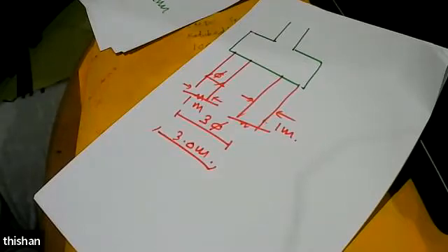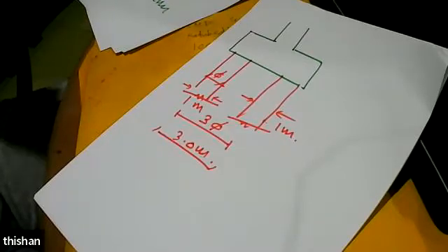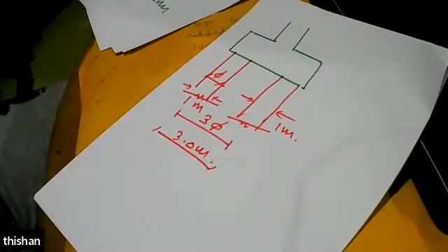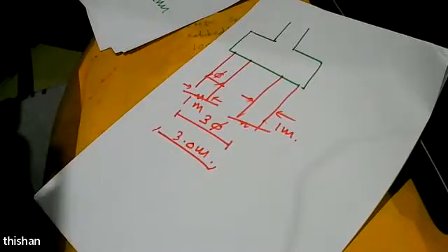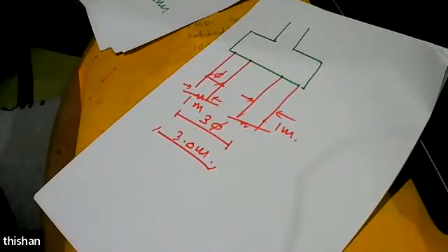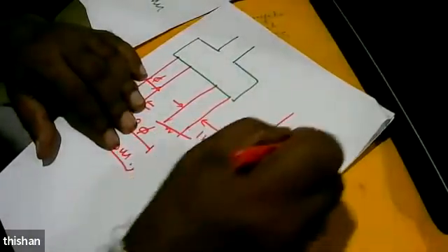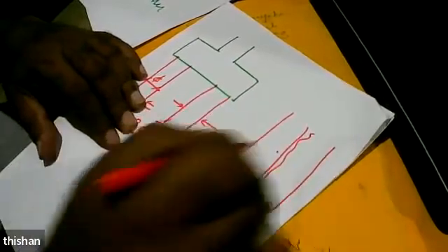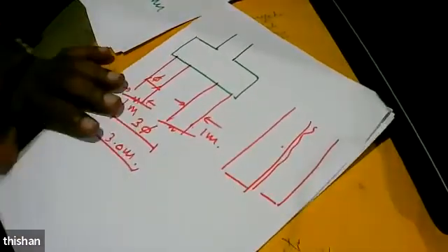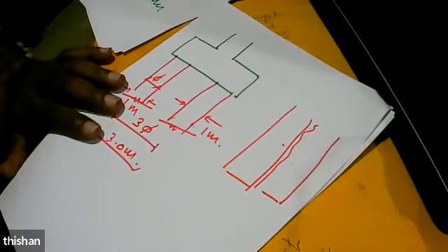So don't try to break the bedrock very close to me. Why? Already this first pile shaft is filled with concrete and it's not very highly hardened concrete. It's just fresh concrete. So you have one socket going that way, and you try to do another socket here. This concrete is not hardened, and you are breaking the rock here. You can have problems.